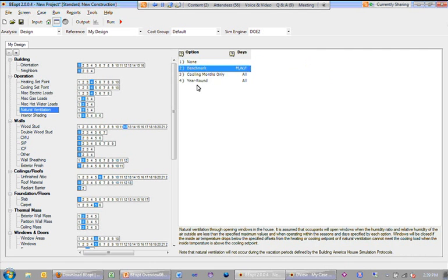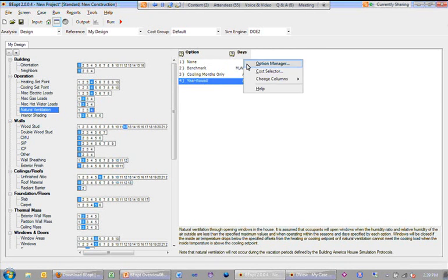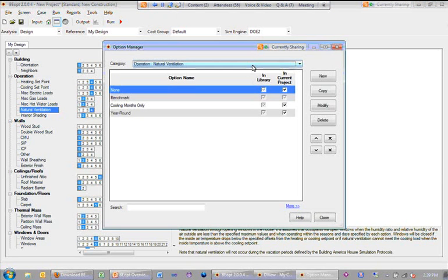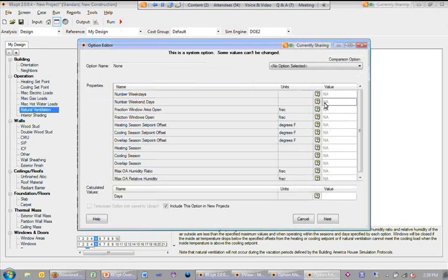If you select one, you could select properties, and you could probably configure it to operate like an economizer, so that it's always available. I imagine you're talking about something with a sensor where it would bring air in when the temperature outside is below a certain point.